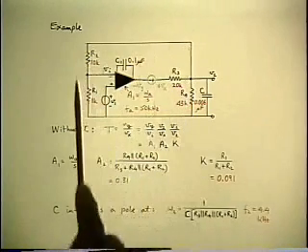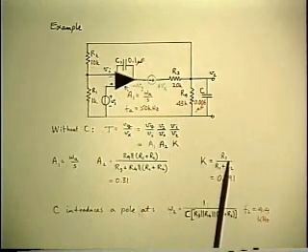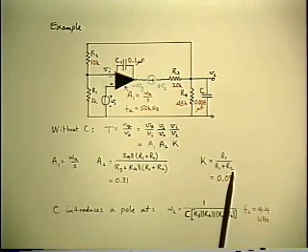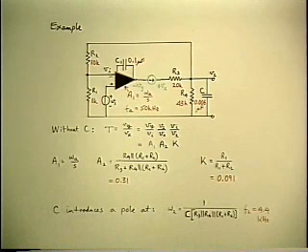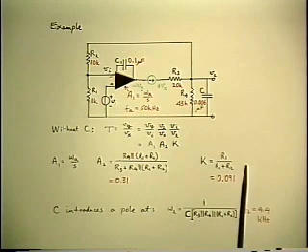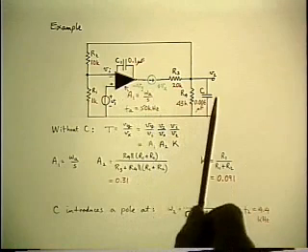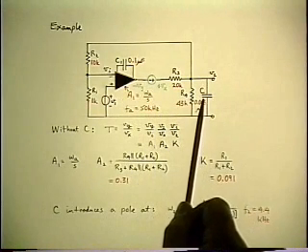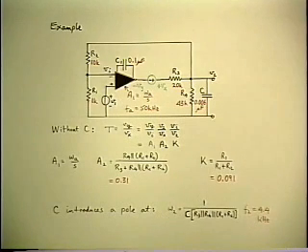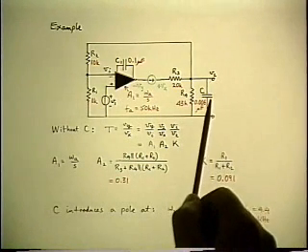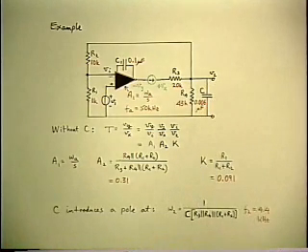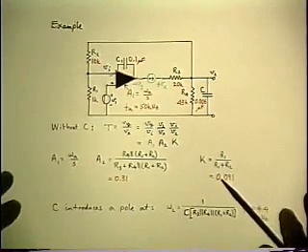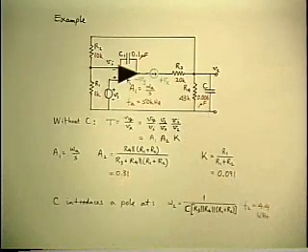Then the K factor is the feedback factor, which is the simple resistive divider, R1 over R1 plus R2, and the A1 is the op amp gain we have already. So I multiply those three factors together, and that gives me the loop gain, except I still have to put back the corner frequencies from the capacitor that I left out. Now, I left it out by replacing it with an infinite impedance, because it's in a parallel position. So again, mentally, we can go through all the steps of applying the theorem in order to restore it.